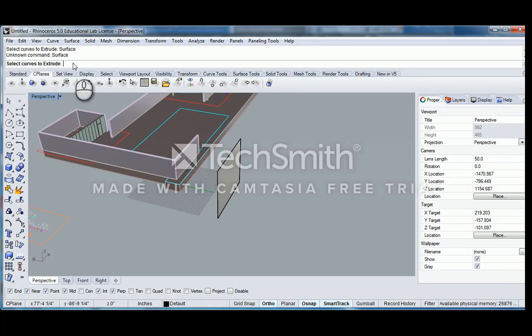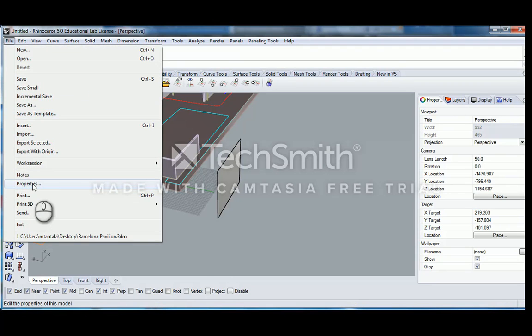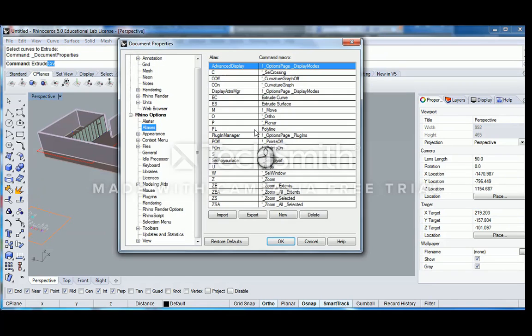So it looks like it got to, in the same way that when we type in extrude, the first thing that comes up is curve. So I was fortunate in this case that my shortcut for extrude curve happened to be what this was. But if I actually wanted this to be extrude curve along curve, it wouldn't have worked, because as soon as there's a space, it ends the command. It ends the macro.